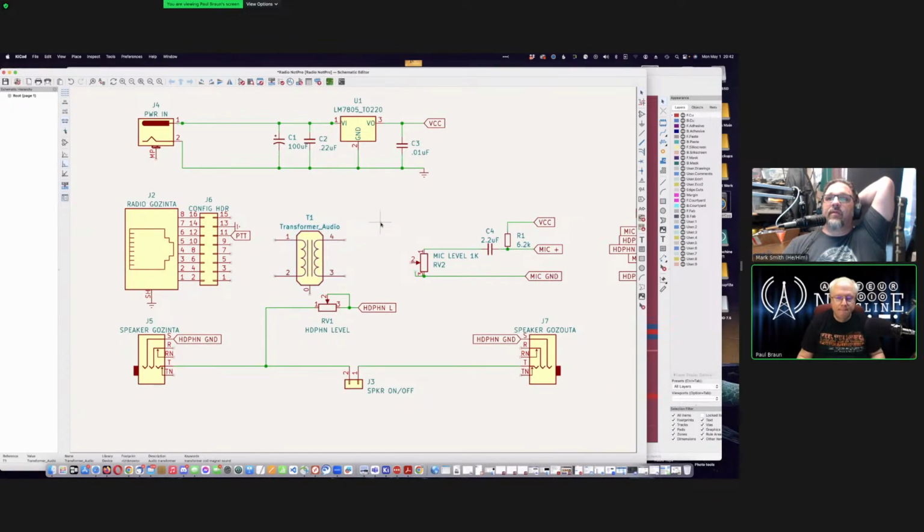Okay. Go ahead and wire it in. I think it was pins 7 and 9. The other advantage to using the audio isolation transformer is that it does not matter which one is ground now. Because audio is coming from the right toward the left.